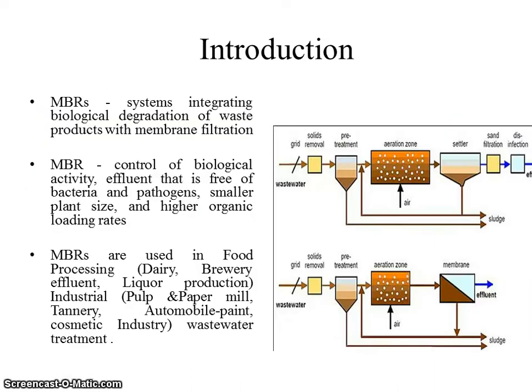In this image you can see the quality of wastewater that you have to subject to MBR: you only have to do solid removal and PST, aeration is still optional, and then you can fix your MBR. Thereby you can bring down the number of treatment units in a treatment facility.